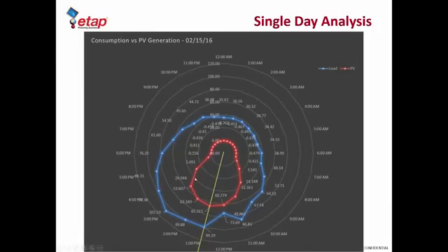The PV generation starts around 9 to 10 a.m. and it's maxing out around 1 to 2 p.m. and it starts dropping off till it gets to about 5 or 6 p.m. And we are in the winter to early spring months, so we do see the sun come up a little bit early and then set around 5:30 p.m. So that's why you will see the output dropping that fast, at least in this location.